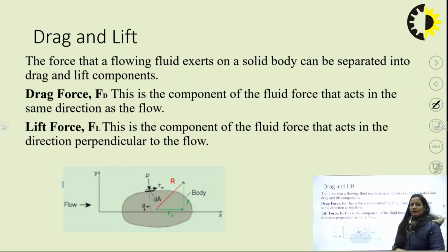The drag and lift, again, as we continue about this concept: the force that a flowing fluid exerts on a solid body can be separated into drag and lift components, as we talked about already. So what is drag force? It is the component of fluid force that acts in the same direction as the flow. And what is lift force? This is the component of fluid force that acts in the direction perpendicular to the flow.